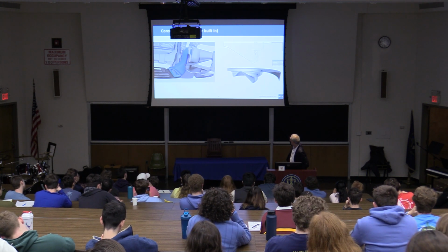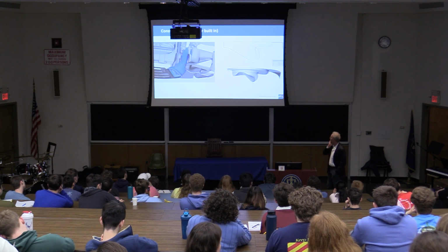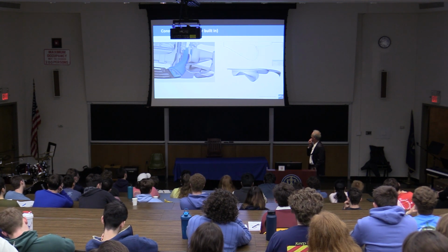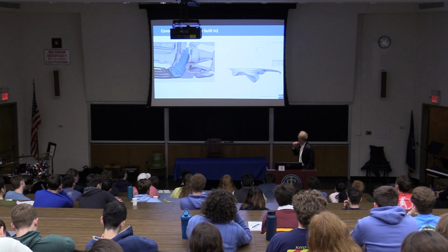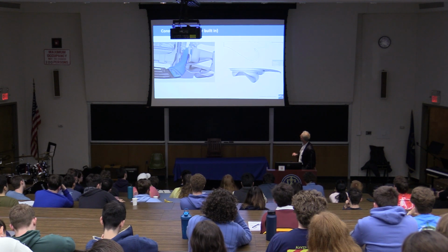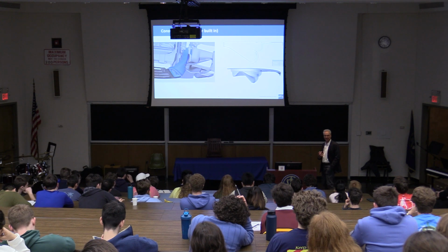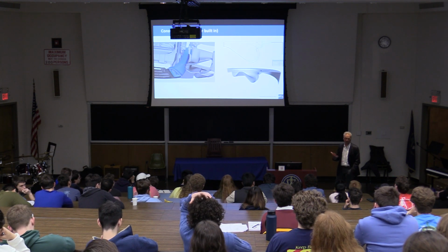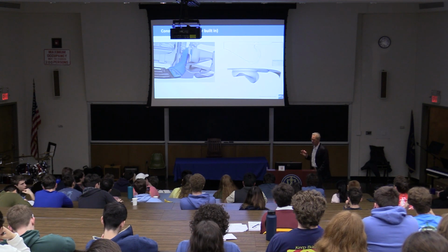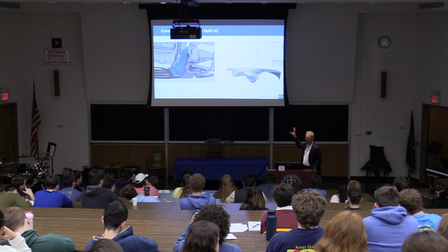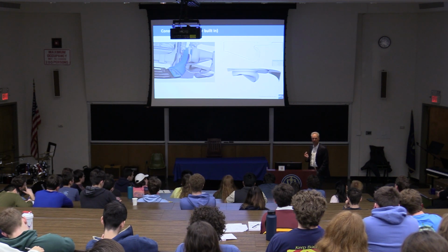Or it's also from automotive industry. It's a piston bowl. Typical example where you need, if you have a diesel engine, for instance, and some of the larger engines in naval architecture are, of course, diesel engines. If you want to do an optimization, you have to keep displacement here. It's crucial. Otherwise, you would compare apples and bananas. So it's an equality constraint where every single geometry has to comply with the constraint of this is your compression ratio, and that has to be constant.